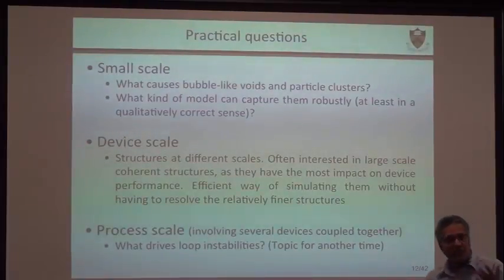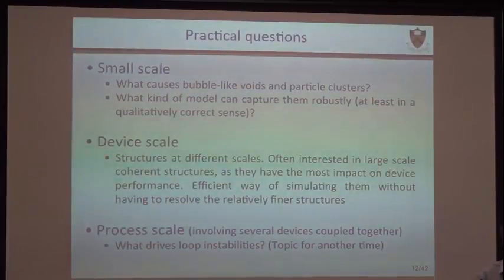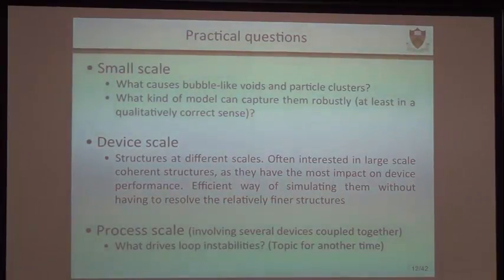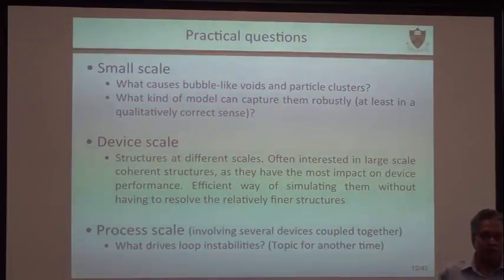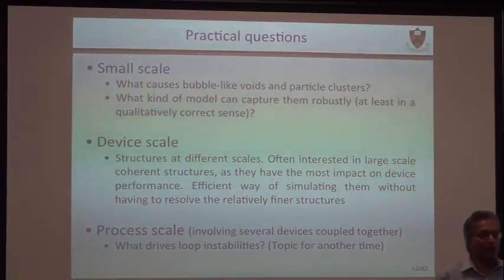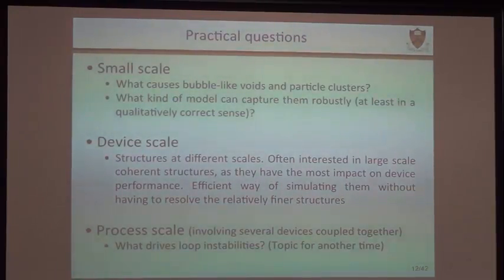If you think about the big picture questions that have driven fluid particle flow research in the last 20 years, we can talk about questions at the small scale. These are what causes those bubble-like voids that I showed you before, and the clusters that I showed you before, and what are the minimum physics that we need to put in to be able to capture those flow problems. And people do direct numerical simulation, particle resolved simulation, particle dynamic simulation, to address and learn about these kinds of questions.